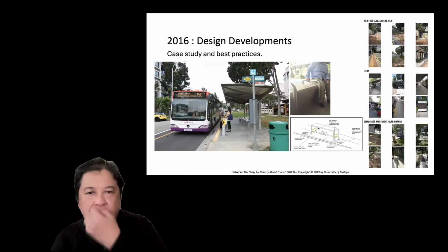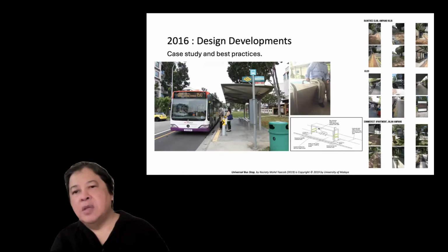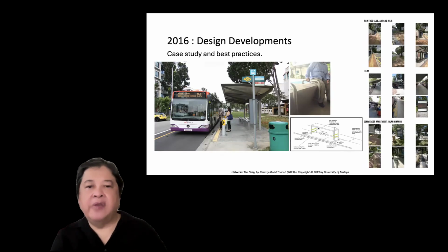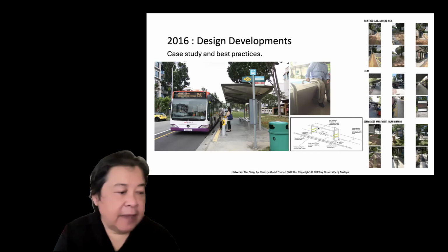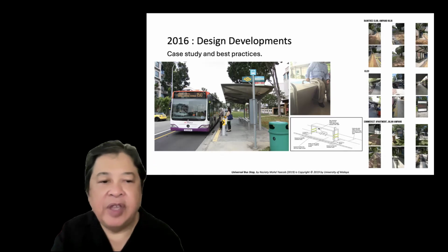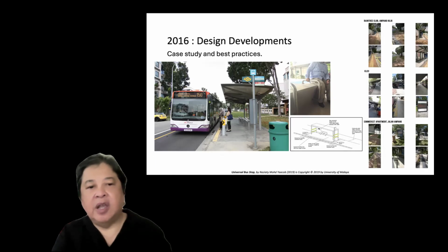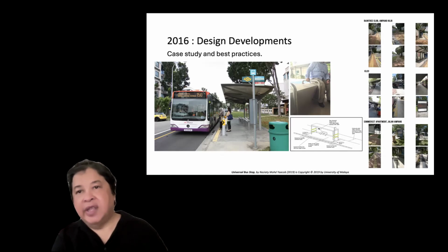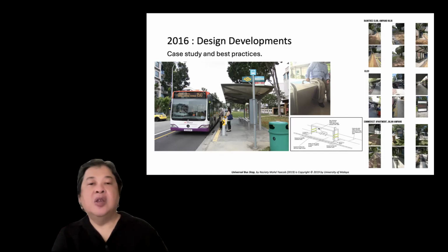The universal design principles that we have include a design that provides for low physical effort, which is one of the universal design principles. The grab bar at the benches is extended out so that we can push ourselves, propel ourselves easily. So we incorporated that. And then there's a free flow of going into the bus, the interface between the bus and the front of the bus stop. Apart from that, the bollards are designed well, because you can't have the bus going onto the pavement accidentally and hitting people. That's why we need the bollards, rather than guardrails, which may impede going in and out of the bus. So we need to be very sure where the entry and disembarkation points are.